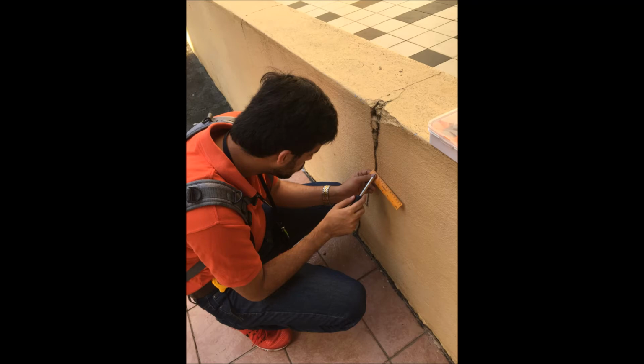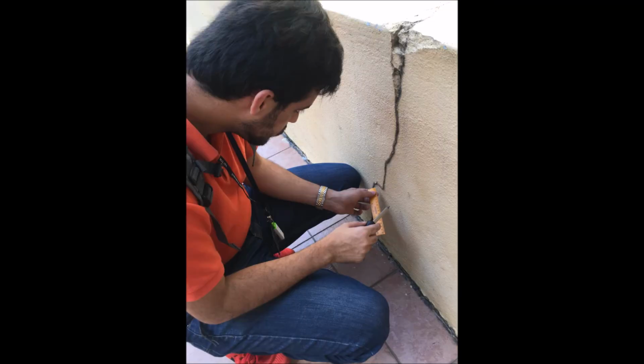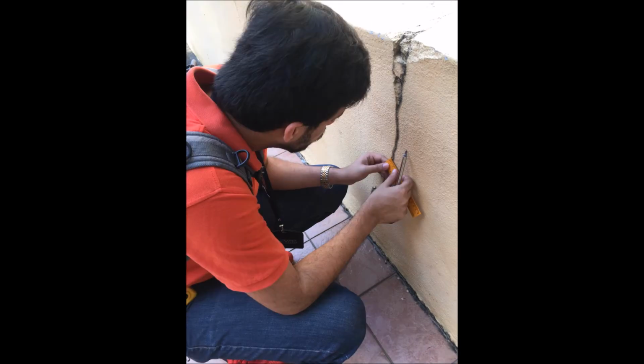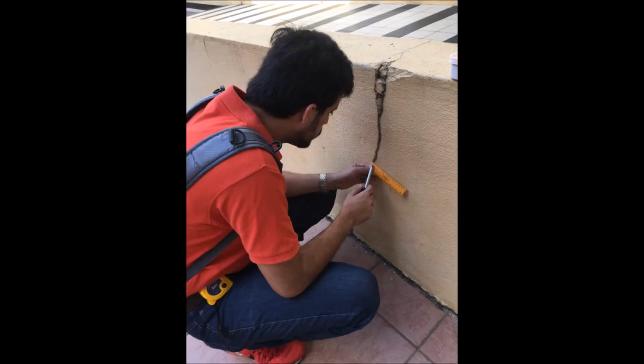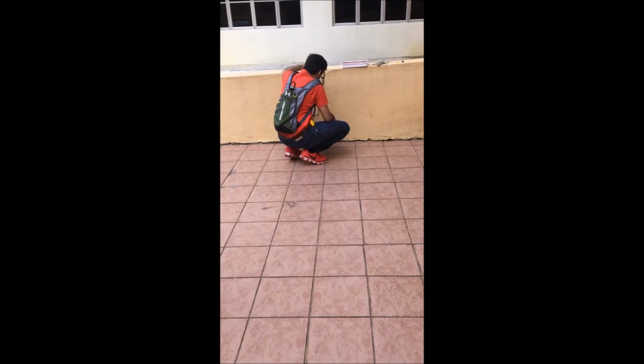The best course of action is to use a Sika 215 crack filler, which could be poured by using injections or could be filled by using a scraper. It would fix the crack, as well as stop it from cracking further.